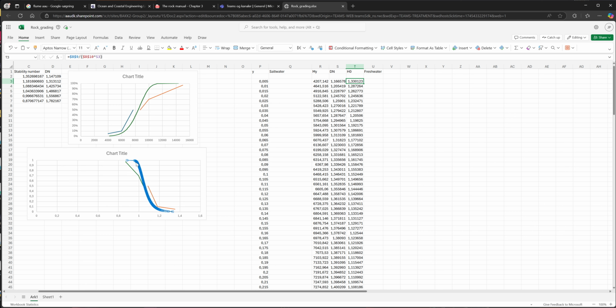We can see the same down here. Having larger stones, there's a lot more acceptance for larger stones than for smaller stones, as we can see here. And this makes somewhat sense, because larger stones will typically be more expensive and better for armoring for large waves.